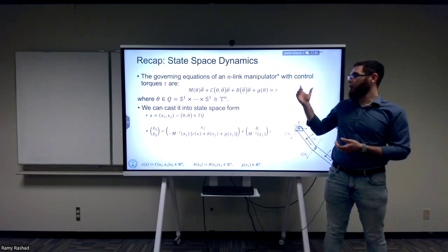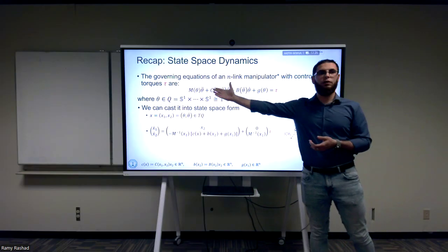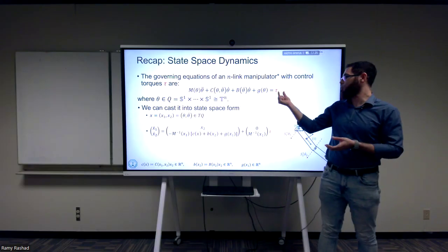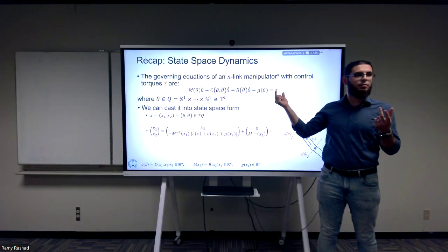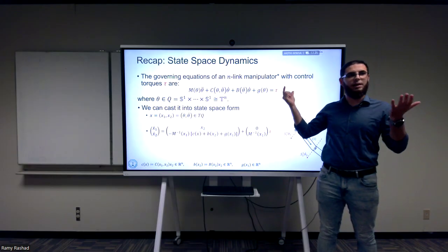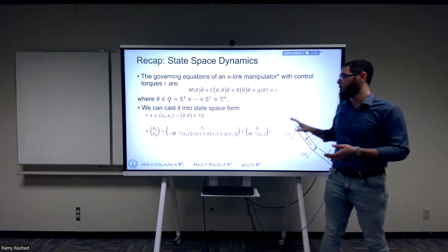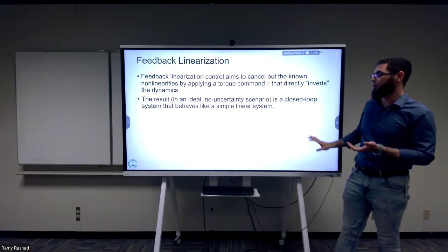So if we can use the torque to cancel out all of these terms, we're going to be left with some linearized system that we can design. And what is the best thing to do with a linear system? Design a linear PD controller, and it will make everything stable. So that's the whole idea of feedback linearization.